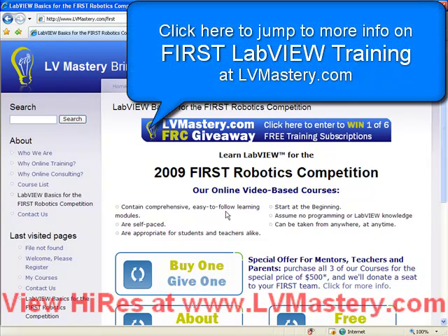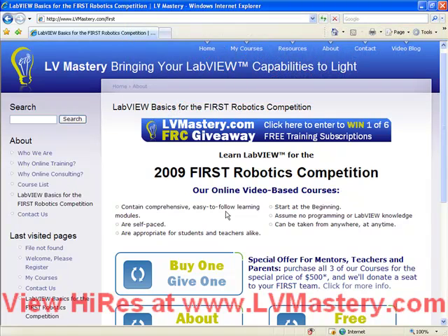In this installment, we're going to talk about some common techniques and shortcuts which will make wiring your diagrams cleaner and faster, and we're going to talk about modularity. We're going to talk about modularity from 2 points of view. First, from the point of view of typedefs, and secondly, from the point of view of SubVIs.